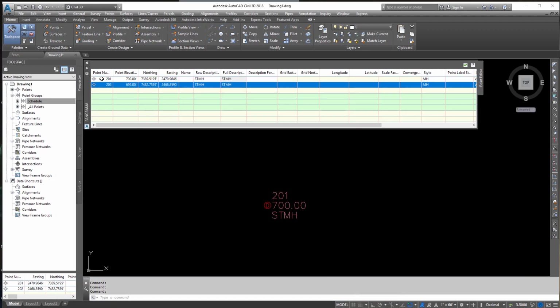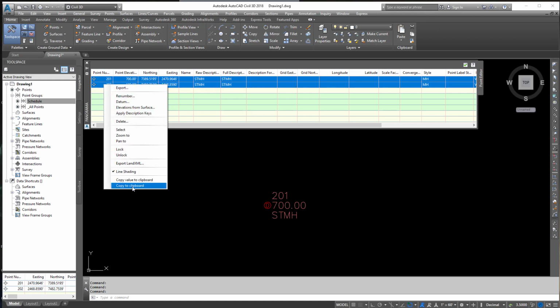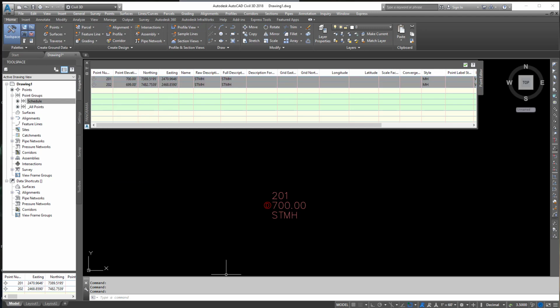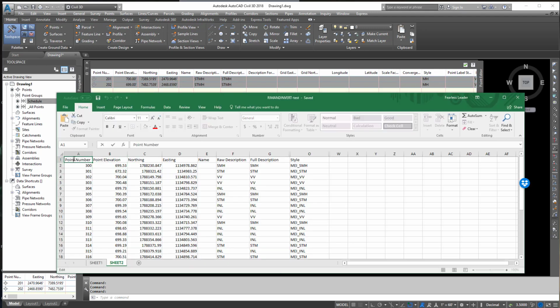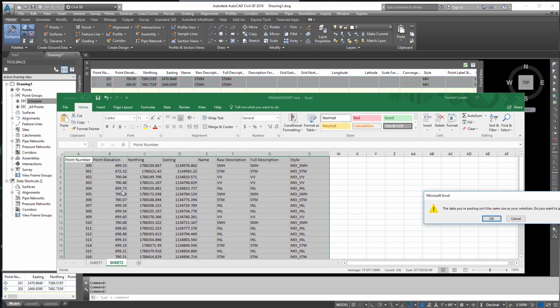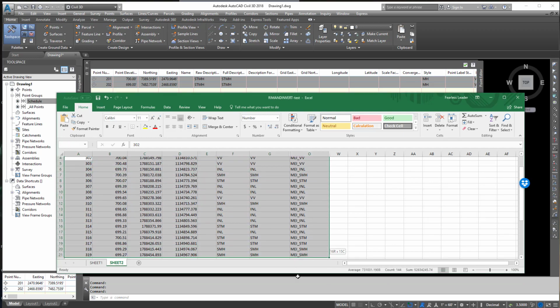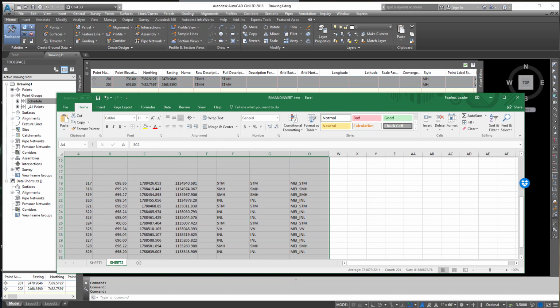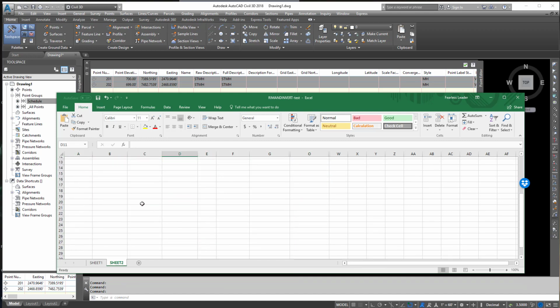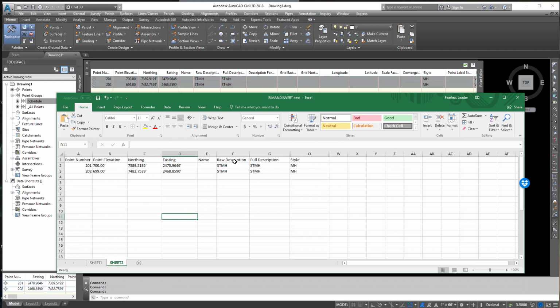Now I'm going to copy these in. If you just hold shift and then right click and go to copy to clipboard, not copy value, we want the whole thing. So copy value to clipboard. Then we're going to come over here, and honestly I just come up in this top left hand corner and I hit Control A, and then I hit Control V. So I do a quick copy and paste. I will hit OK, and then I erase out the extra stuff. Now you'll notice that these are all in here now, and I usually do a quick spot check, make sure everything's coming out good, and it is.